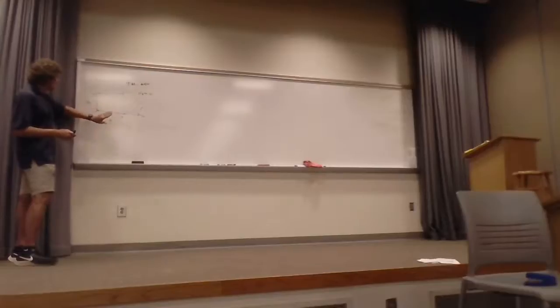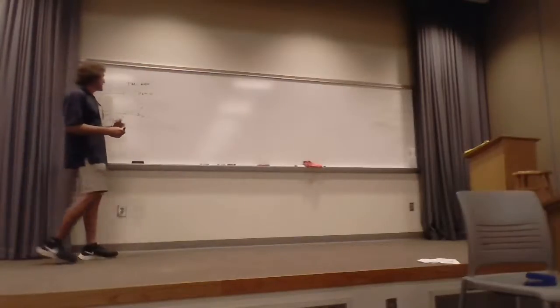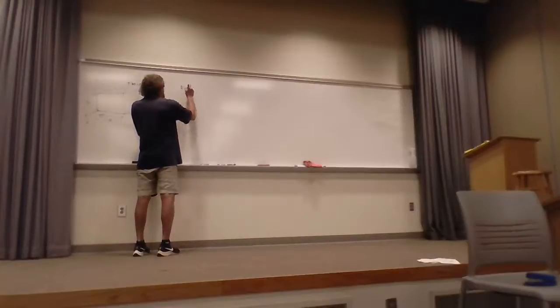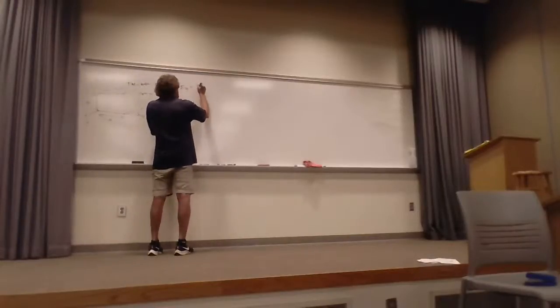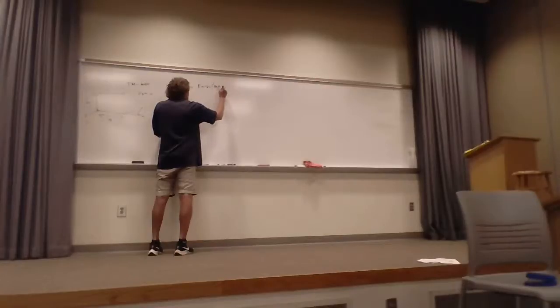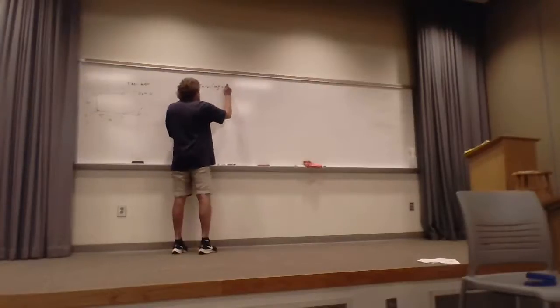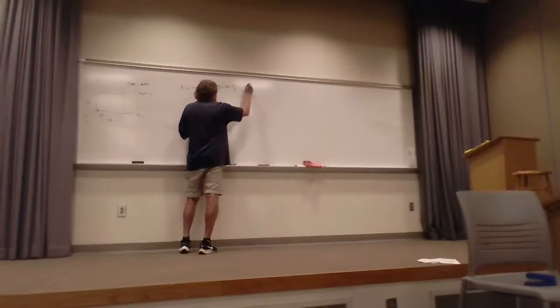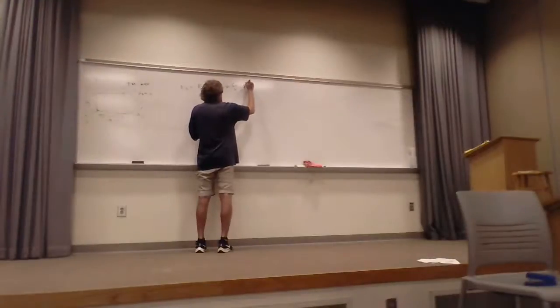So that's the dimensions, and for TM, H_z equals 0, and we found out that E in the z direction was equal to some scalar value, we just call it E naught, times the sine of m pi over a times x, times sine of n pi over b times y, times e to the minus j beta_z z.